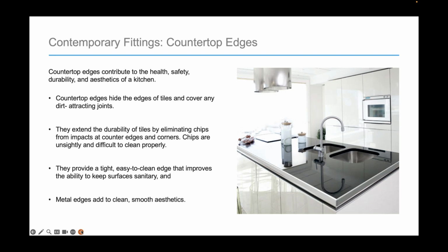We also have countertop edges. Countertop edges contribute to the health, safety, durability, and aesthetics of the kitchen. Countertop edges hide the edges of the tile and cover any dirt-attracting joints. They extend the durability of the tiles by eliminating chips from impacts at the counter edges and the corners, and chips are unsightly and difficult to clean properly. They provide a tight, easy to clean edge that improves the ability to keep surfaces sanitary, and also the metal edges add to clean, smooth aesthetics.